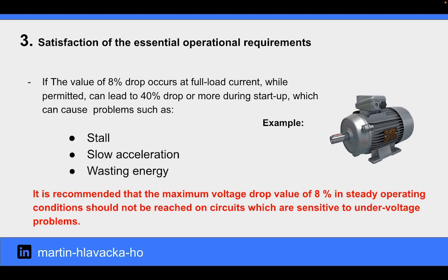Or third, continuous loss of energy, which for continuous loads will be a significant waste of energy. For these reasons, it is recommended that the maximum value of 8% not be reached under stable operating condition in circuits sensitive to undervoltage problems.